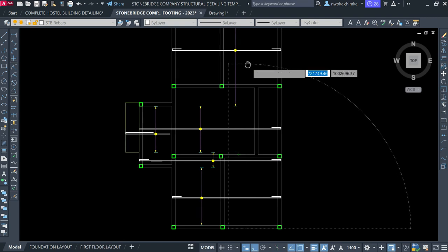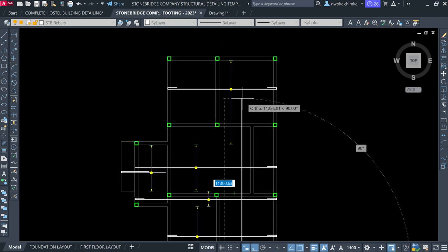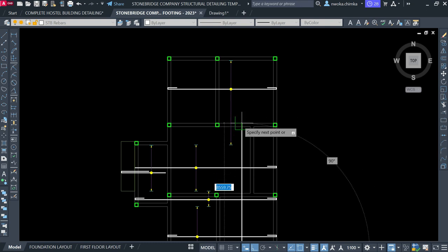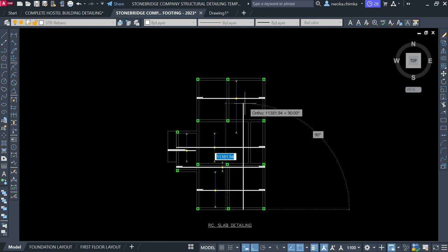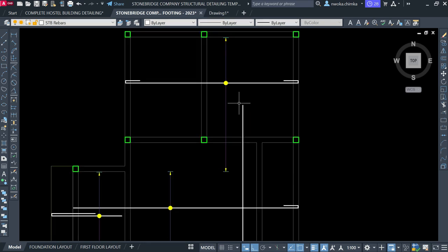So right now I'm at 10.751. Okay, I'll go here again, and just for this, I can go and stop at 11 meters. Okay, so I'll just type 11 meters, and then enter. Sorry, that's not 11 meters. Sorry, undo, Control Z. Okay, and then type 11 meters, which is 11,000. Okay, that's fine. Enter. So this now is where it stops, as you can see there.